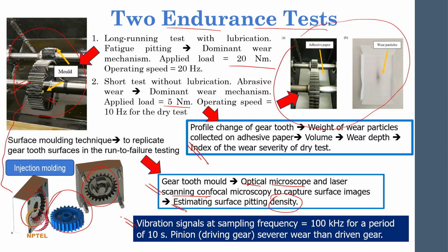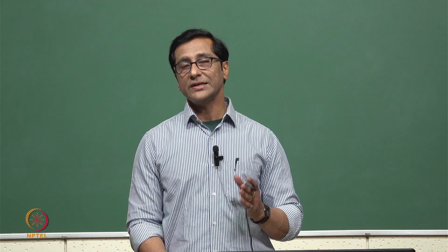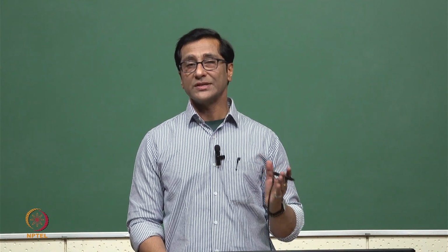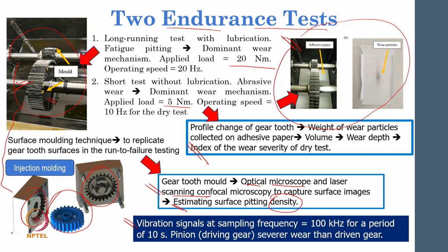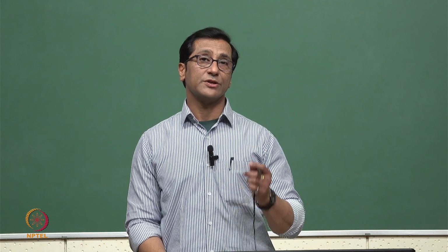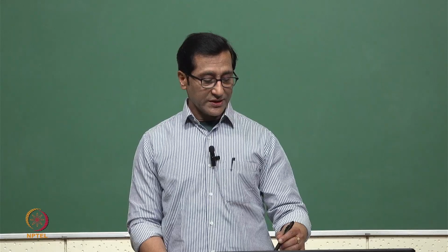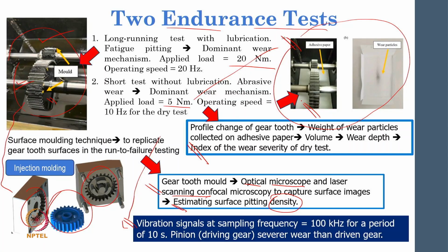In addition, they try to collect the vibration signals, because finally vibration signals need to be related with wear loss and the pitting density. So if we are able to relate the micro vibration signals, then in future whenever we operate in a real situation, we will be getting a vibration signal, and based on the vibration signal we need to understand what is really happening in a dry case, what is happening in the lubricated case.